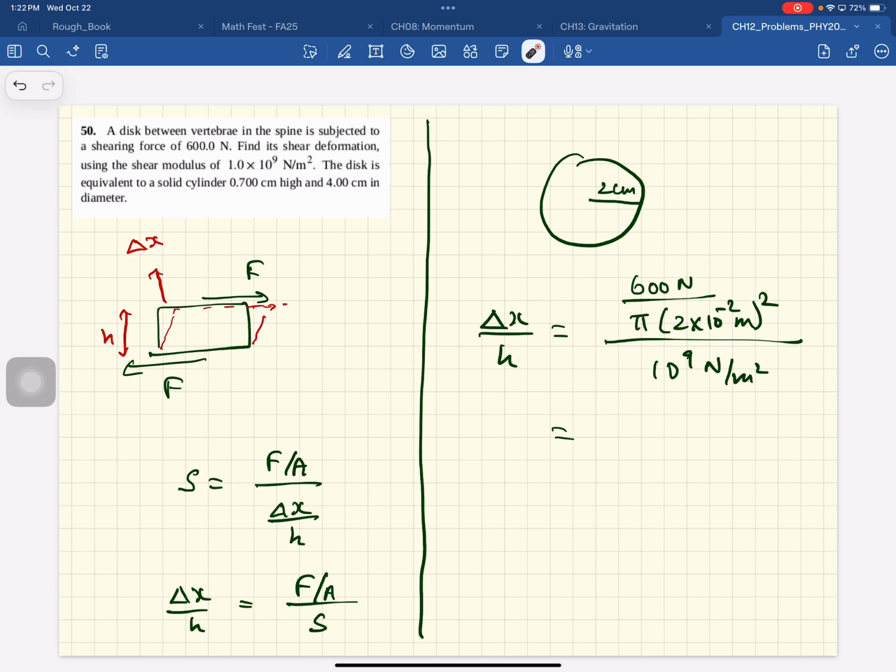All right. Anyway, am I good to go? Okay. So you see, this is dimensionless, and this is a percentage deformation. The stiffer the material, the smaller this number will be. So for metals, let's see what this number comes out to be. Delta x is a deformation in this direction, and h is in that direction. You understand that the thicker the book, for the same force, you'll deform it more. For a greater height, this will be greater.